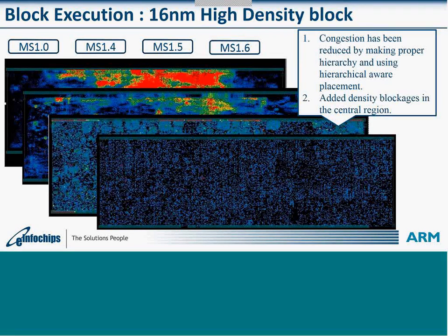And there are a couple of techniques also explained here: it was forced as a hierarchy driven placement, as well as a lot more density blockages were added in that central region, so that the cells will spread apart.